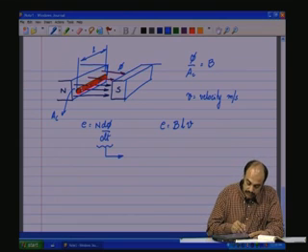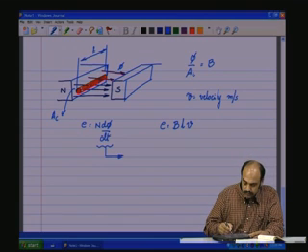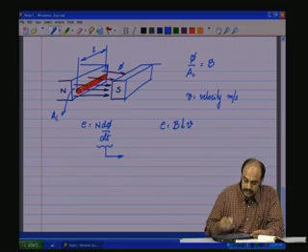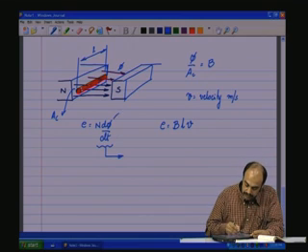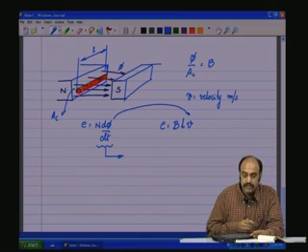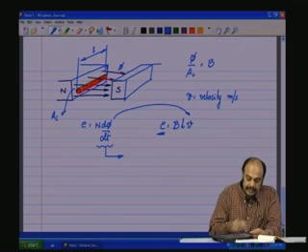This is what is cutting the flux, and as it is moving, it is at various radial and angular distances from the center, and thereby the flux amplitudes are going to be varying at different positions. That is going to cause the d phi by dt effect, and it is going to result in an induced EMF in the conductor.